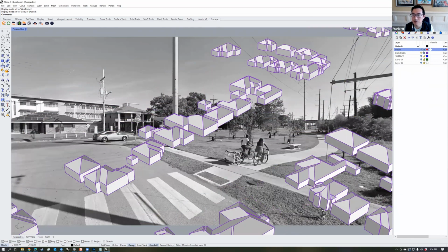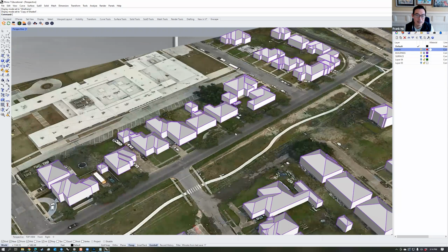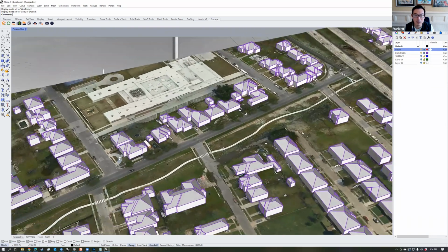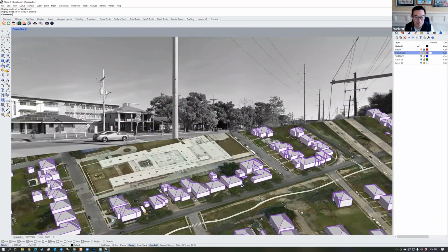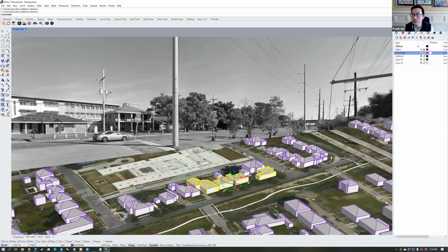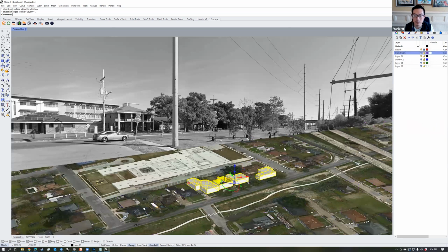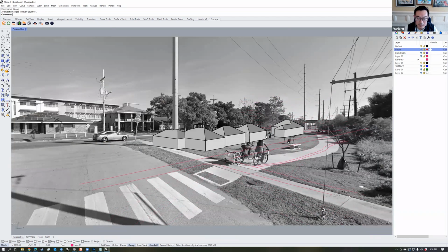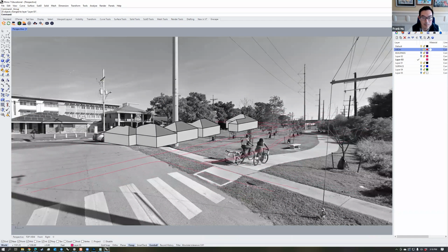So basically what you do is you need to align the buildings within that frame to the image here. So this building, that building, that building. And I'm just going to move that to a new layer temporarily. So change object layer, then turn off everything else. Now we can use these elements here to align the image to the actual model line work.